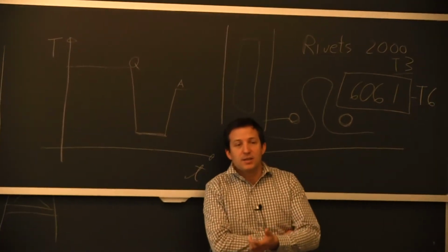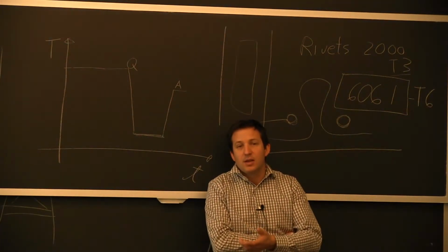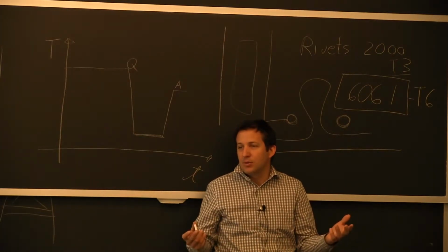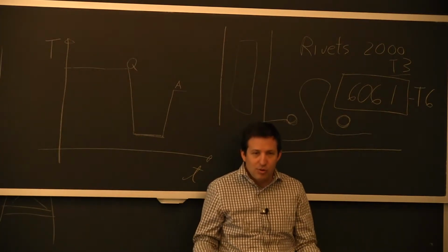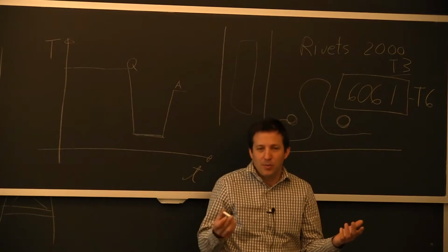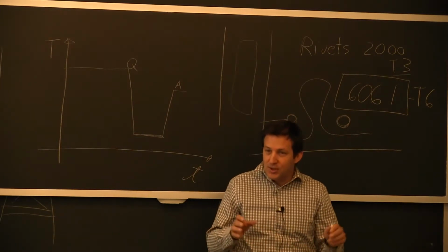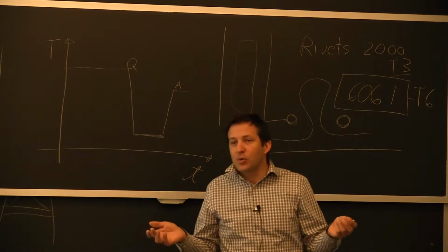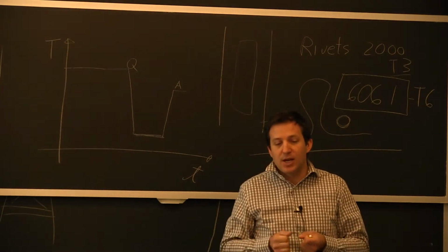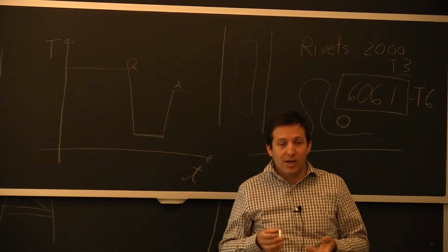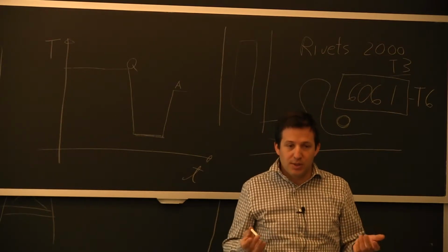There are a lot of things, and you're not taking into account fatigue. You're just assuming that if you have a material that's 4 times stronger than what will make it yield, you're going to be okay. Which means you can't weld it any way you want if you're going to have a lot of water hammer or pressure fluctuation. Otherwise, you're going to have a failure.